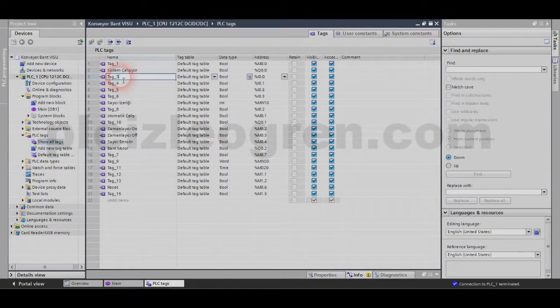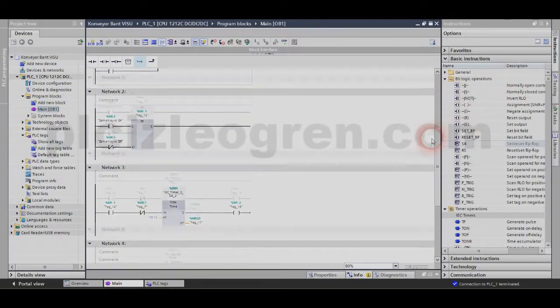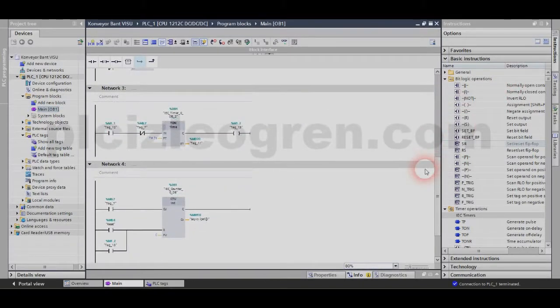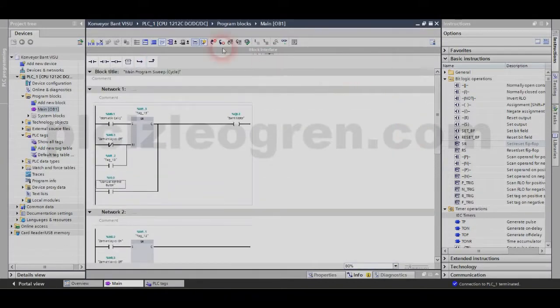This is important. Our 01 is here. Let's call that manual control button. This will be our manual control button. You can see what is what if you take a look. I have used the Mercury memory field here, and why is that, you think? Because there can be communication problems between this program and the simulator. So, rather than using something like a real key on a panel, I used Mercury memory fields.